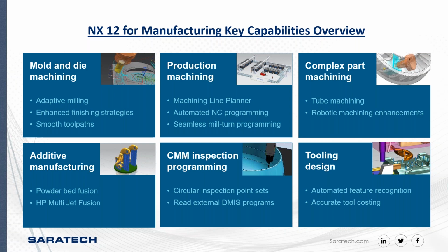Also, they've given us an incredible additive manufacturing module inside of NX for powder bed fusion and HP multi-jet fusions. It's amazing how it has a three-dimensional algorithm for nesting of parts. So it'll give you the build volume, and then at the click of a button, you can do a 3D nesting for however many parts you want, with different tolerances. You can give it a time limit, and it'll try as many different options as possible in that time until it figures the best one out, or it times out, one or the other.